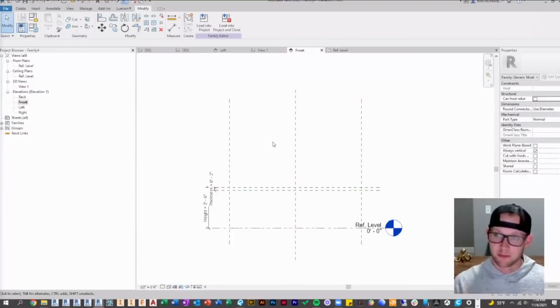Okay, so we kind of talked about all that. This is basically my first best practice. I know this was all very simple, but I'm telling you, if you remember to make a skeleton first, the troubleshooting later will save you a ton of time, because the next thing we're going to do is never constrain geometry to other geometry, and don't just constrain it with constraints. You tack it to the skeleton, right? Like it's muscle on a skeleton.